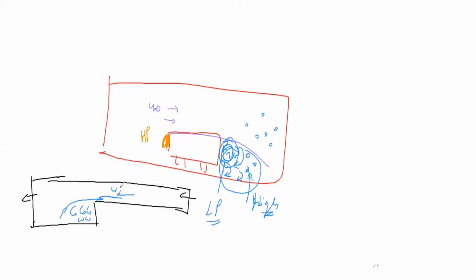Here the velocity with which it is coming will disturb the static pressure. Static pressure will reduce, and it will make the molecules move to the left hand side. In this case, a void is created here, which is a low pressure region, and the surrounding is a high pressure zone compared to this zone. So from high pressure to low pressure, the molecules will get sucked in, and this will give rise to a recirculation zone. That is why recirculation is created here, or in turbomachinery applications, or Ahmed body applications, whatever you take. So these are the things happening, guys.